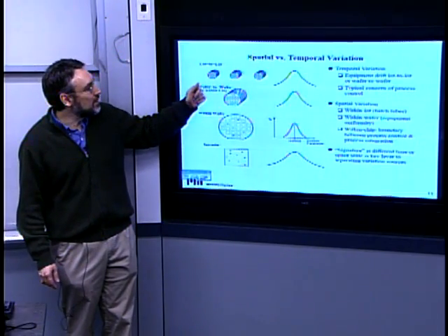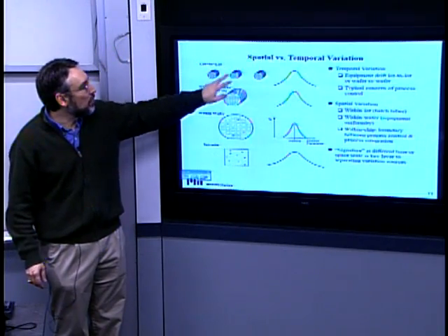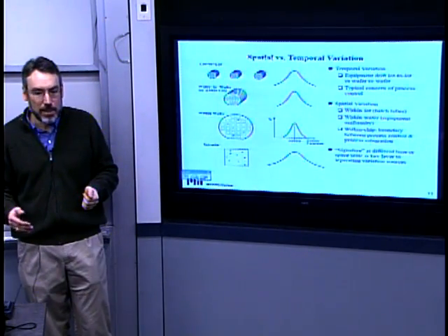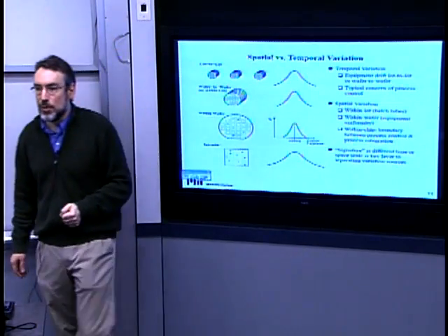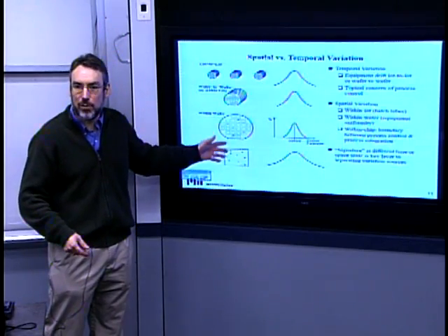And then finally, in semiconductor fab, we typically are processing a lot of wafers that may be 24 wafers at a time, and from one lot to the next, these might be processed at substantially different points in time, and there may be another distribution associated with that, and physical sources or causes of that variation that are different than these other spatial or temporal sources.